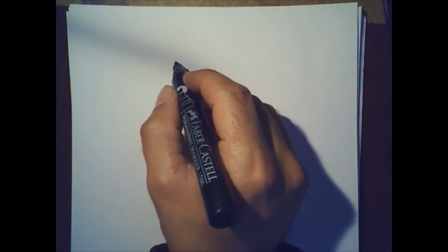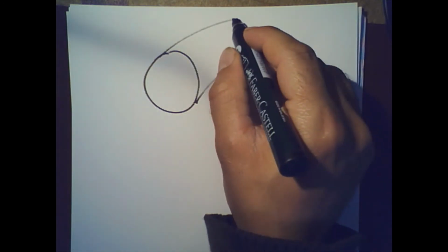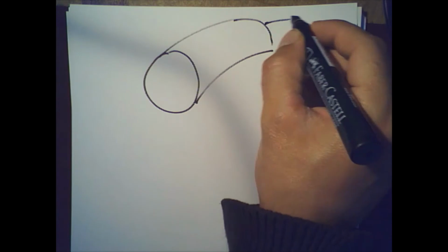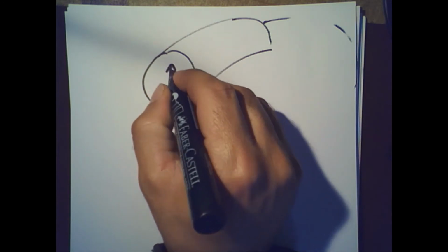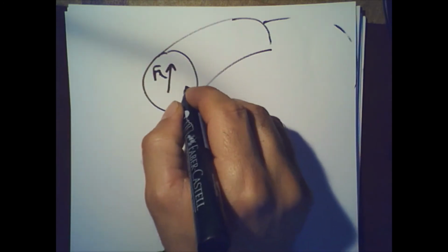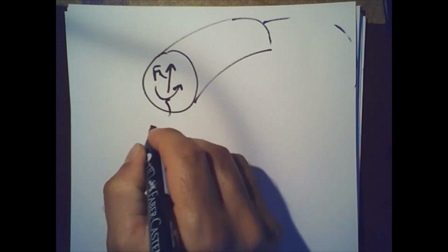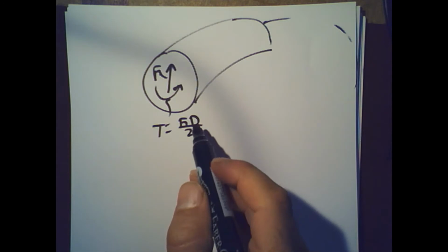Okay, I would like now to do a brief review on the stresses in the springs before I do an example. Let's say this is a portion of that wire which is like a helix, going up, and we said here you are going to have this shear force, and you're also going to have a torque applied, and that torque was equal to Fd over 2, where d is the mean coil diameter.